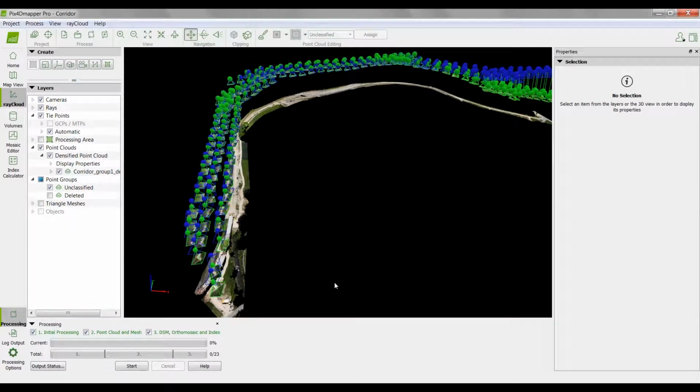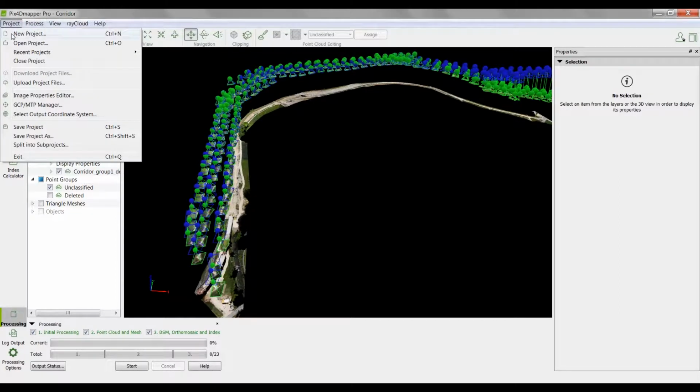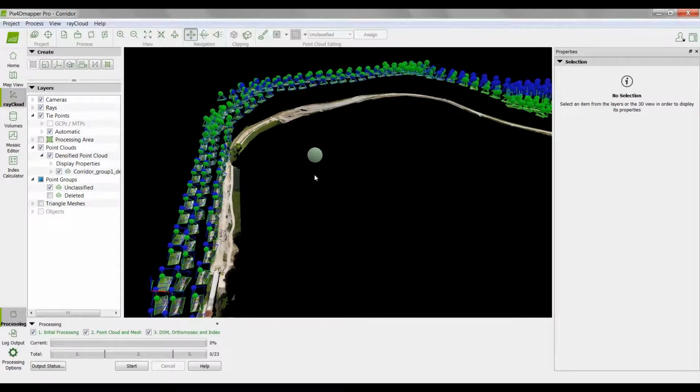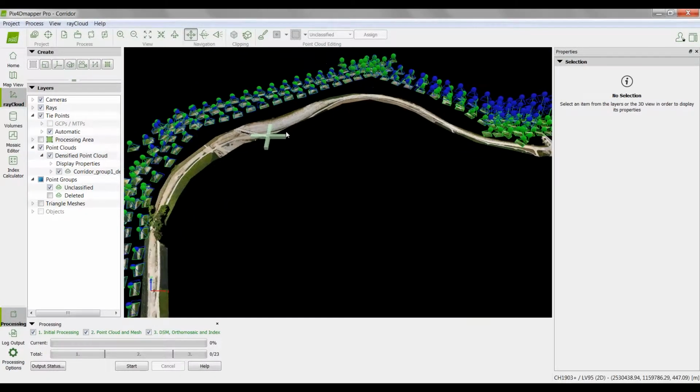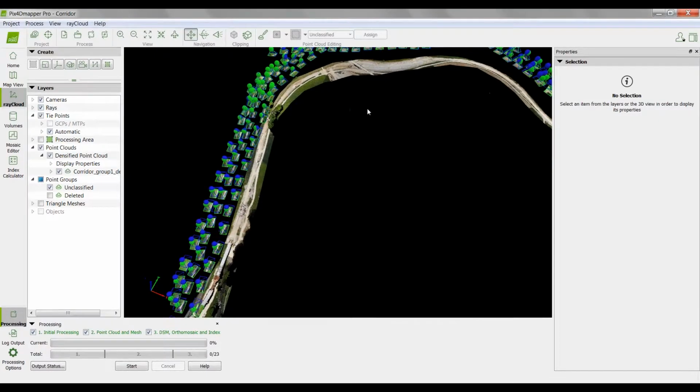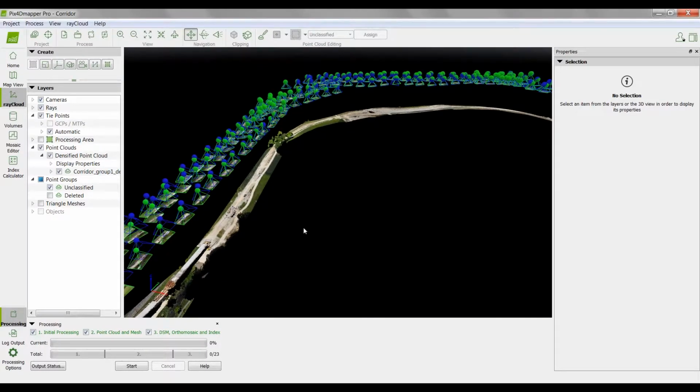If you manage to do this in one flight, then eMotion will create for you directly a Pix4D project. If not, you just create a new project here, giving it all the geotagged images, and with that, you'll be fine. Potentially, if you manage to do RTK PPK, it's not necessary to do any ground control points. Maybe it would be interesting to lay out one or the other checkpoint to actually evaluate your accuracy.